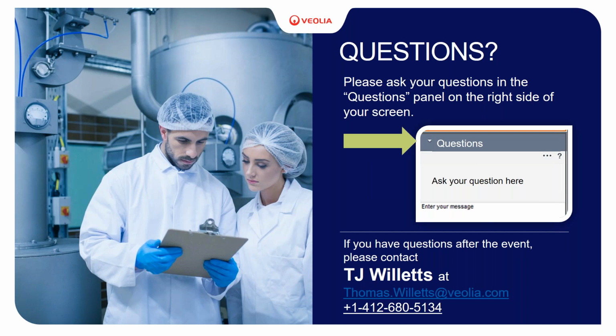Thanks, TJ, and thanks for the question. There's standard toxicity testing that our lab does and several other labs around the country do, where you just send the new chemical to us with the intended use rate, and we can expose it to anaerobic biomass and determine if it is toxic, at least if it has any acute toxicity, by measuring the COD reduction and biogas production over various concentrations of that chemical.